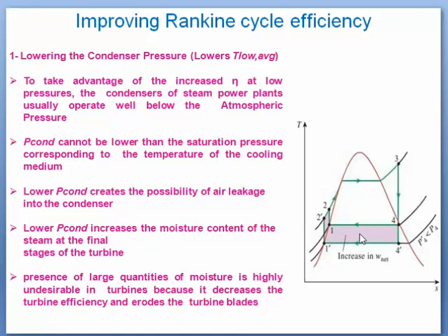But now the question arises: up to what extent can we lower this condenser pressure? So there are certain limitations. P condenser cannot be lower than the saturation pressure corresponding to the temperature of the cooling medium.